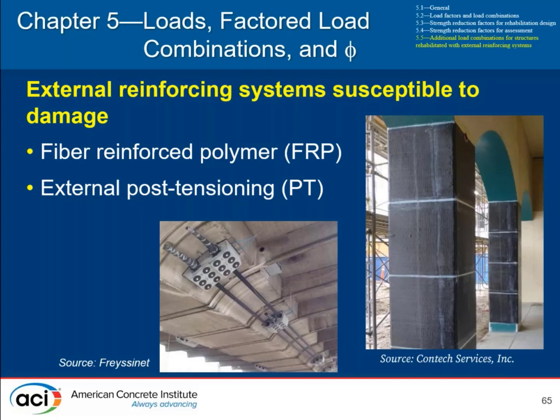If we've got external reinforcing systems that are susceptible to damage, the concern here is that damage might occur and that damage might not be noted for some time. And we want to make sure the structure has sufficient capacity not to be unsafe for that period of time that it takes to identify that damage has occurred and repair the damage.